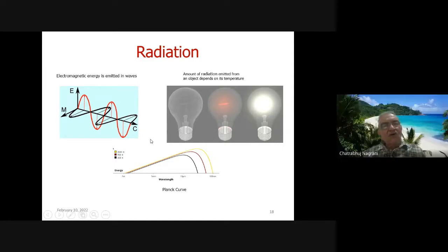See, finally what we are measuring is radiation. As you all know, by Planck's law, as the temperature of a body increases, the peak of the radiation shifts towards lower wavelength or higher frequency. Let us see the bulb. I apply a very little voltage to the bulb, and it will appear red. Then I go on applying more and more voltage, and it becomes white. That means the spectrum, the frequency content or wavelength content or color content, changes.